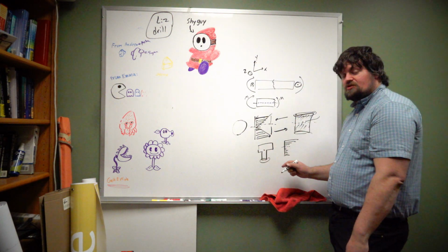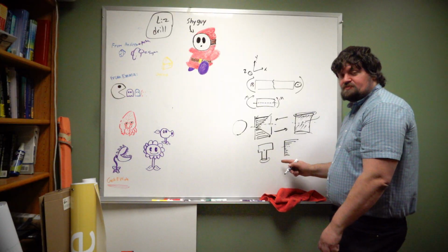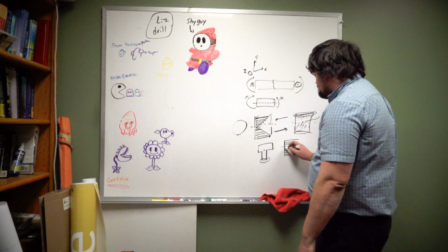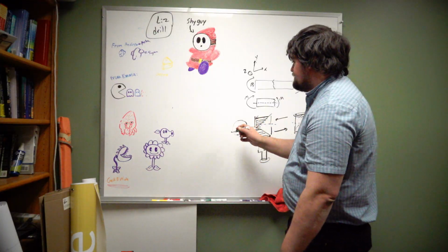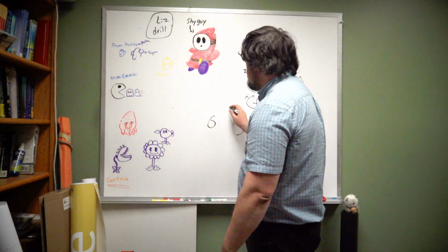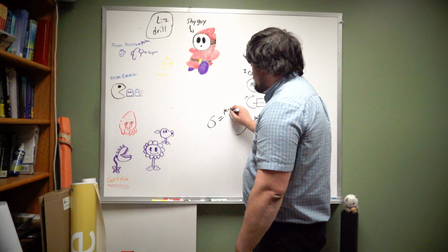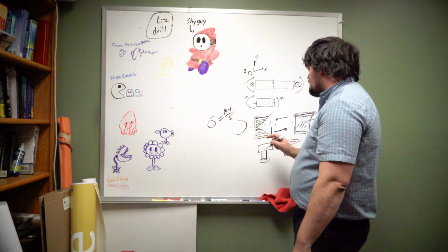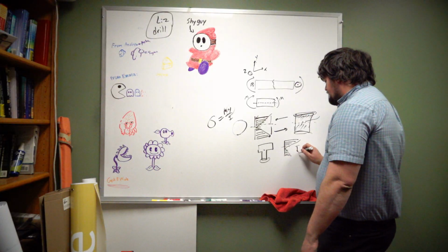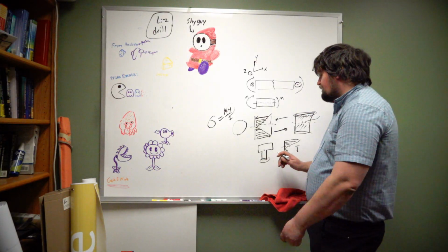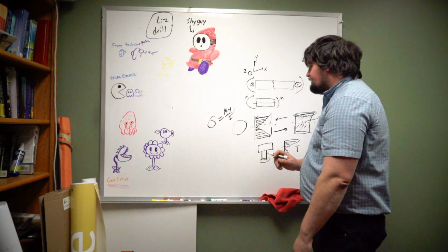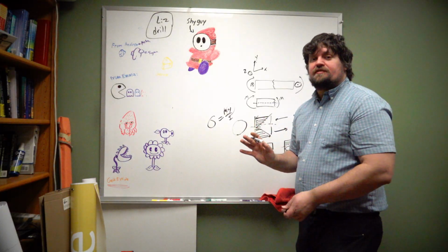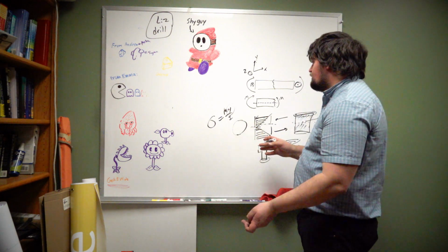Even though it's a smaller amount of load, you have a larger displacement that ends up getting carried in order to cover this weird difference. Because, as you remember, our equation is sigma is equal to My over I. Well, this has the largest y value because here, y value is the distance away from the centroid along the y-axis.